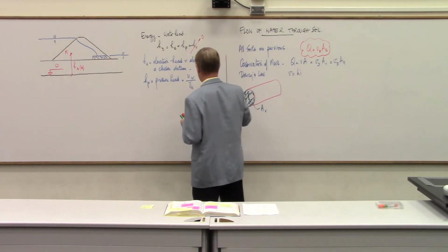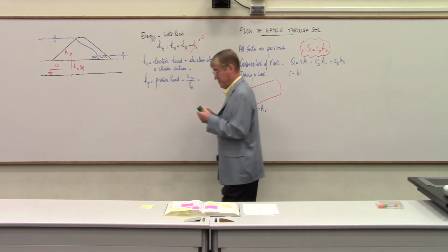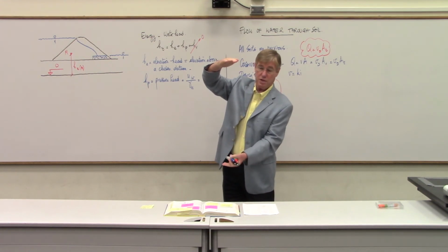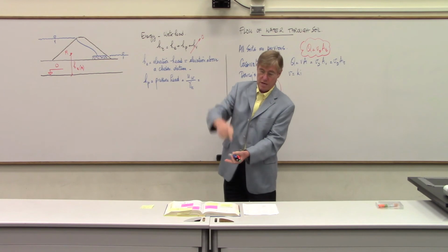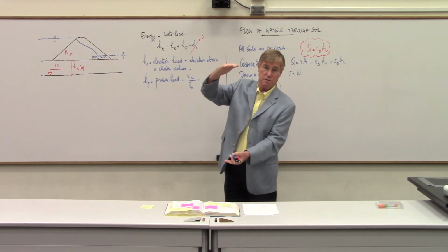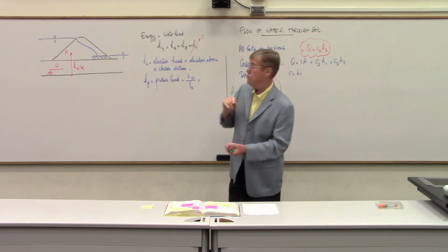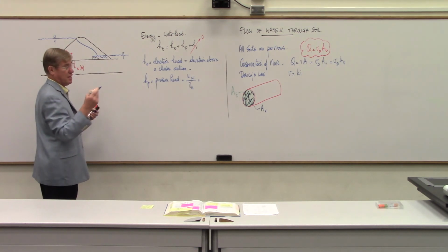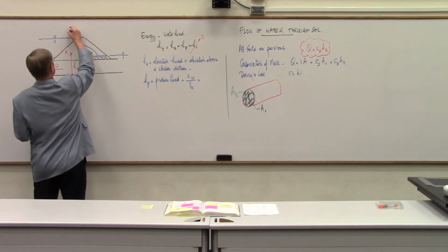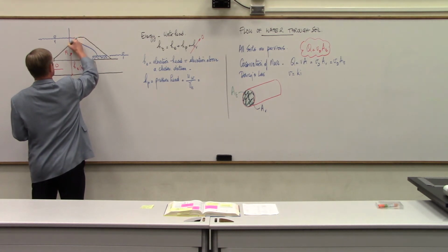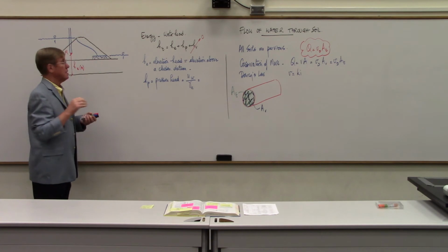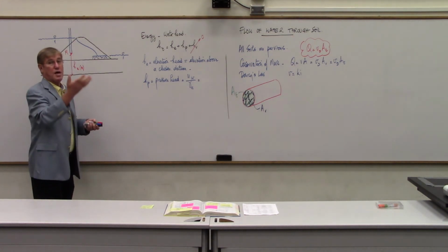So the pressure head, and you know if you have a container and the water is at this level at the bottom of the container, then the pressure is the height to the free water level times the unit weight of water. So if you were to drill, and that's not a good idea in that, but imagine that you have this imaginary pipe that comes down to M, like this. And you connect that pipe to M. Because of the pressure at M, the water is going to rise in the pipe.